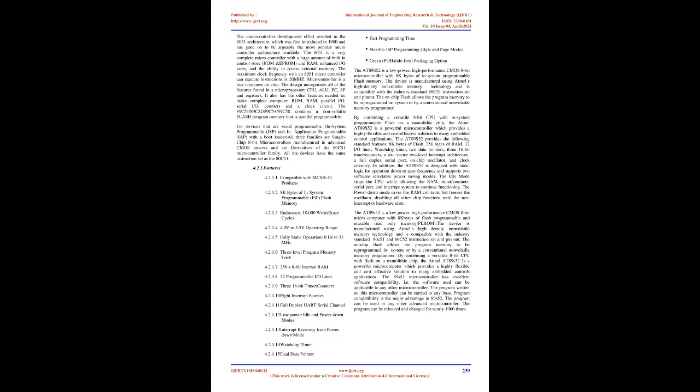4.2.1.4 4.0V to 5.5V operating range. 4.2.1.5 Fully static operation, 0 Hz to 33 MHz. 4.2.1.6 3-level program memory lock. 4.2.1.7 256 x 8-bit internal RAM. 4.2.1.8 32 programmable I/O lines. 4.2.1.9 3 16-bit timer/counters.